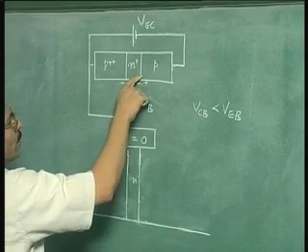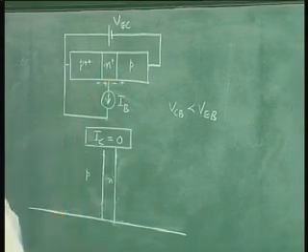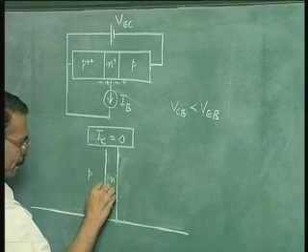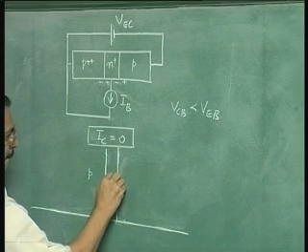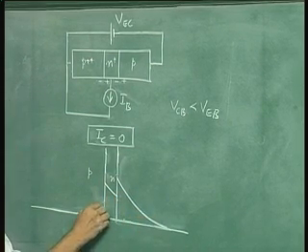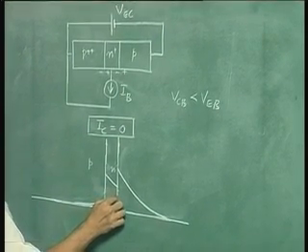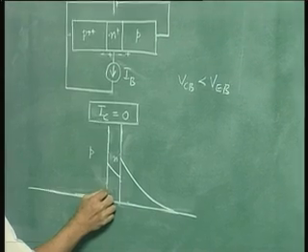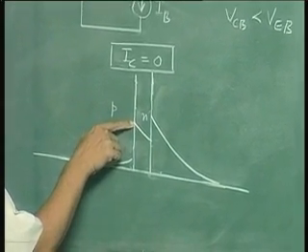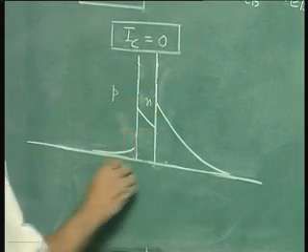So when you want to draw the excess carrier concentration for that condition, it will be as follows. So you see that the collector base forward bias is less than the emitter base forward bias. That is why this concentration here is less than this concentration here, the excess carrier concentration. Okay, this is again we are using the law of the junction.